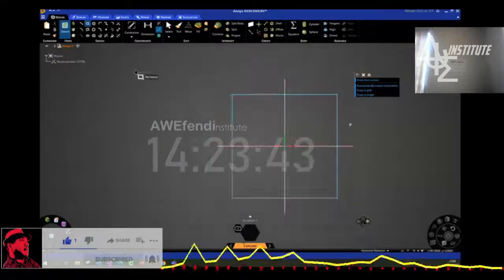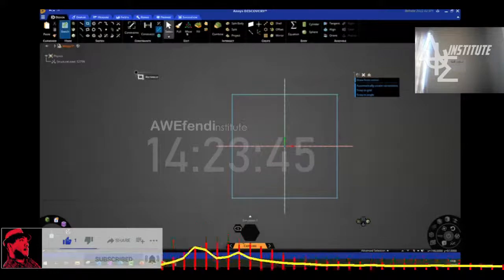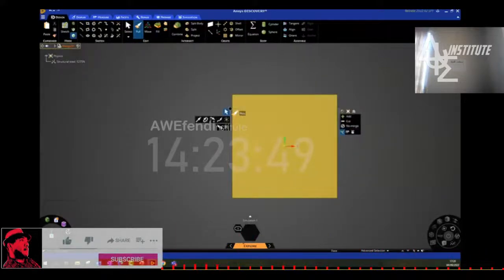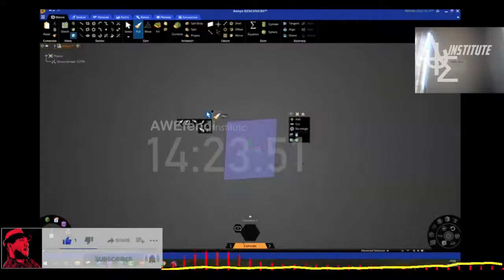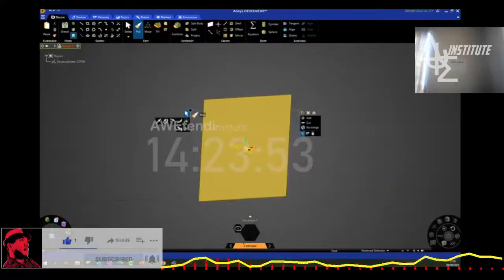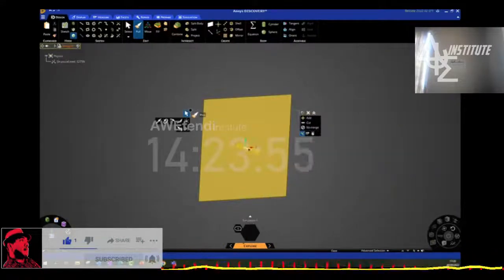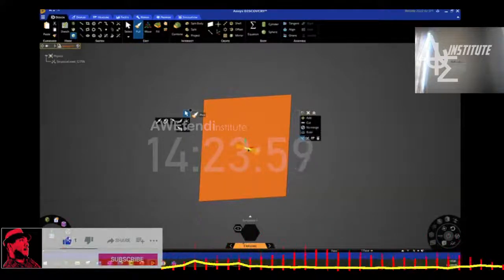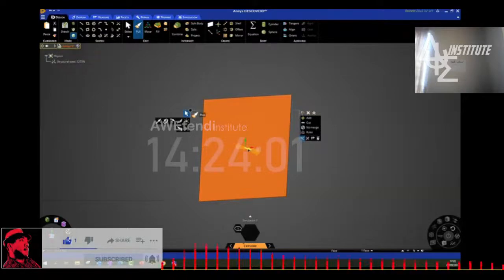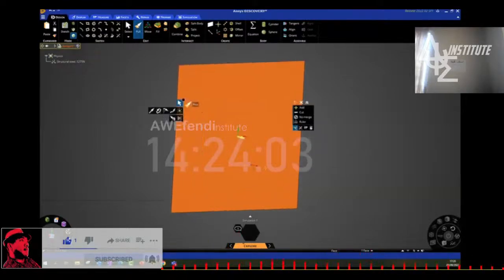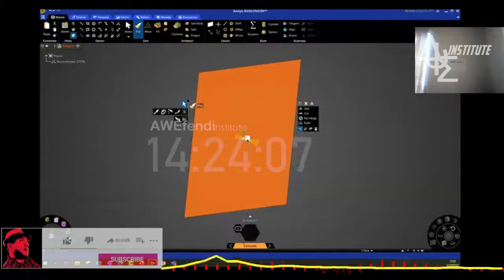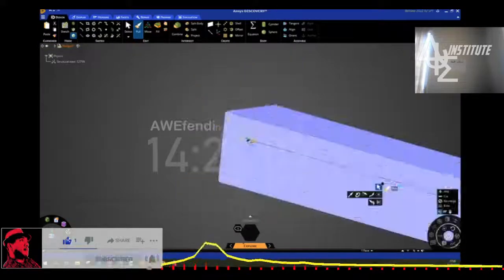Now that we have the cross-section, let's extrude the model. So I use the pull tool over here. I'd like to point out that these options are almost exactly the same as what we have in our flagship software, SpaceClaim. So it's nothing new for you to learn if you've already used it. Now I want a length of 1000 millimeters, so I give in that value.